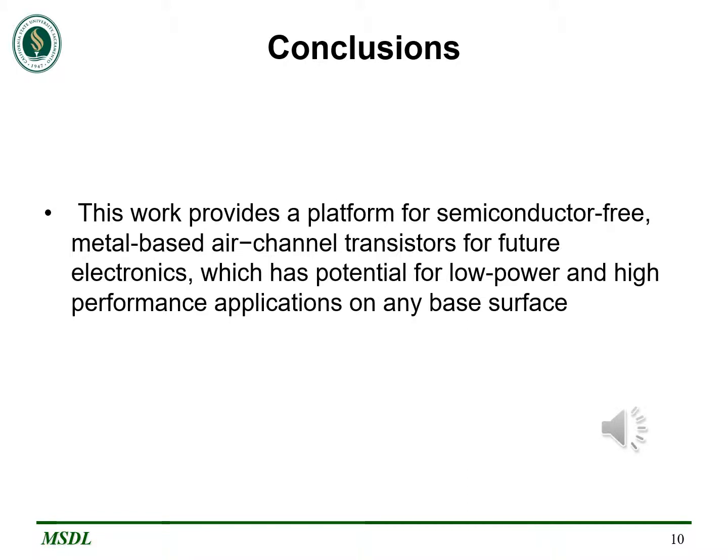Experimental data shows that Fowler-Nordheim tunneling is dominant in tungsten and gold, whereas Schottky is dominant only in platinum. Forward bias current is higher than the reverse bias current when the device experiences Fowler-Nordheim tunneling, while it is of the same magnitude for Schottky emission under the influence of gate voltage.